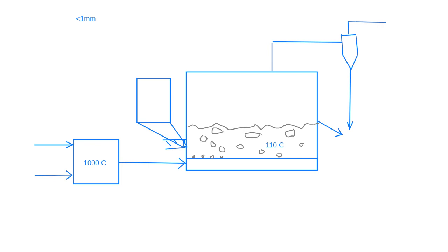the sensible heat that's in these hot gases, will be transferred to the bed, and that sensible heat will do the latent heat evaporation of the water, and it will also be heating up these wet particles. It'll be heating up the particles themselves. It'll be heating up the water, sensible heating, up to 110 degrees C, and the latent heat evaporation of water will also be involved.